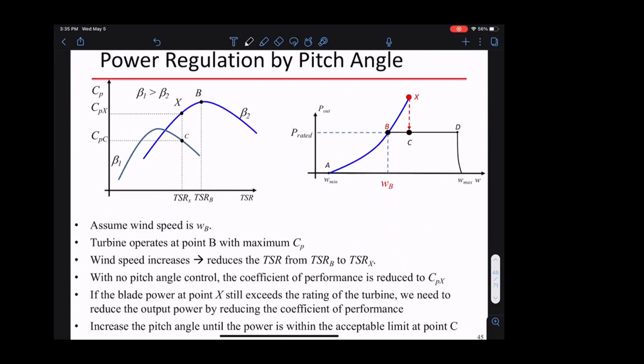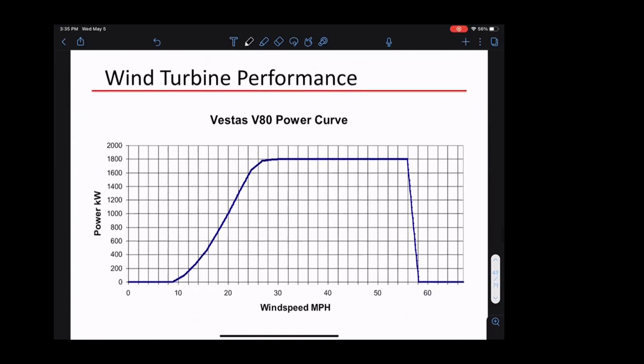And if you go out and buy a turbine, you'll get a data sheet that will tell you, given different speeds and the turbine type, this is a curve that you have to follow. Anything lower than this curve is possible. You can generate at any power lower than the curve. Anything higher than the curve, you cannot do. You cannot operate at a point above the curve, although you can operate at a point below the curve. So this is turbine generation.